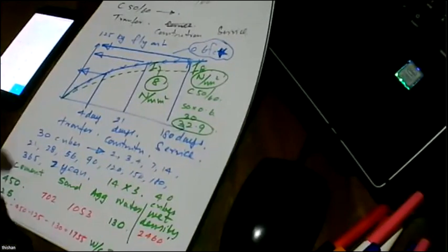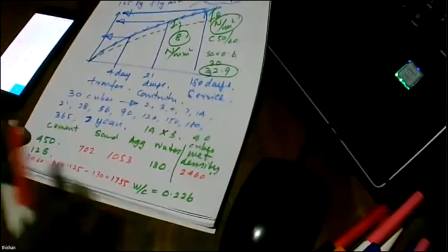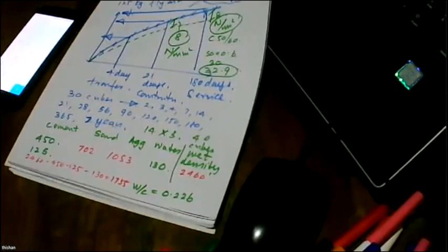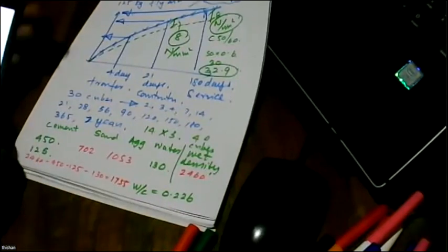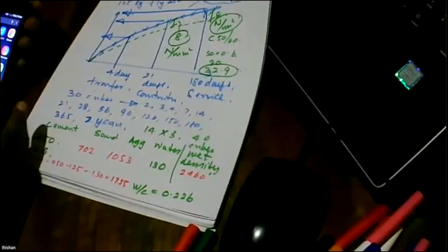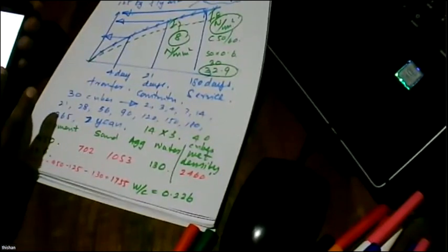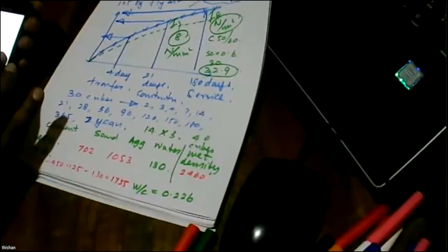Once you go for a logical mix, because these strengths are very high, you have to go for a very low water content to achieve it, because the only way you can achieve it is by using this kind of very high grade super plasticizers, and they are actually manufactured in Sri Lanka by Mr. Ravi Nissanka.